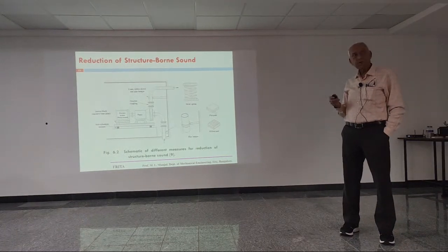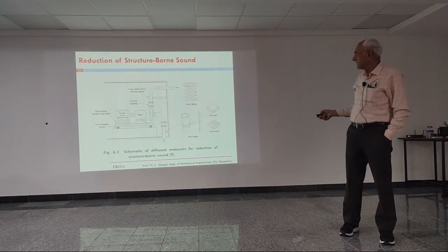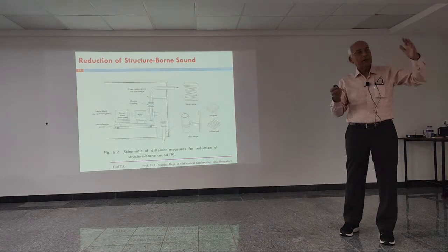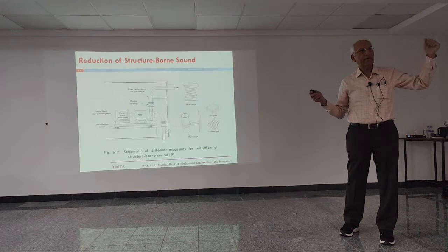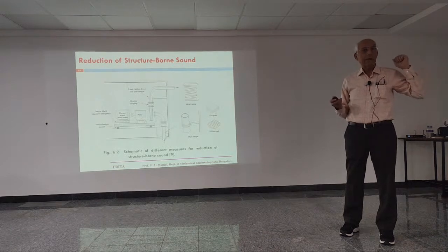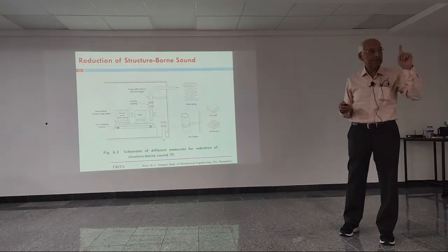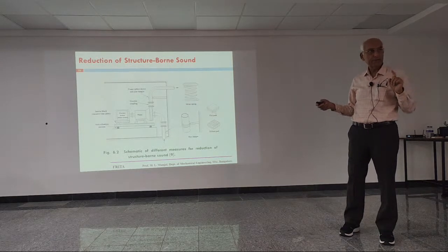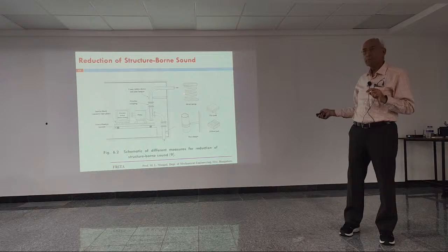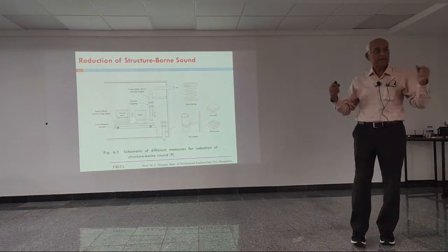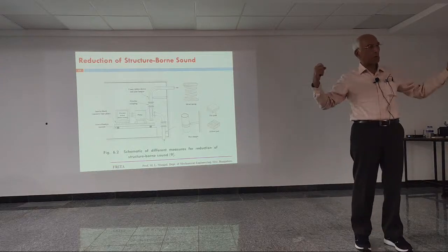But let me tell you one thing: if the mass is more, that is a machinery kind of thing, and you need good vibration isolation, the best thing, please note, is a metal spring. A metal spring can take much more load.